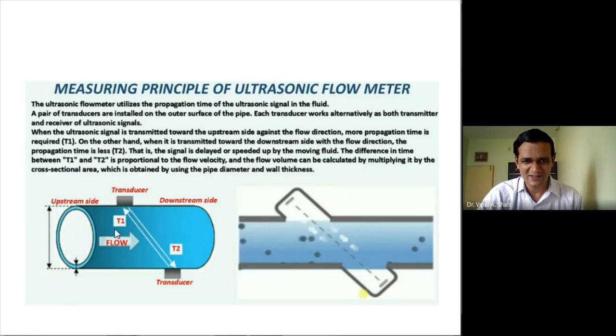As the blood flows, this transducer applies ultrasonic waves, which are reflected back and received again at the transducer. So you can find out the total time traveled during this period, and then you can scale it to monitor and maintain the blood flow measurement of the human body.